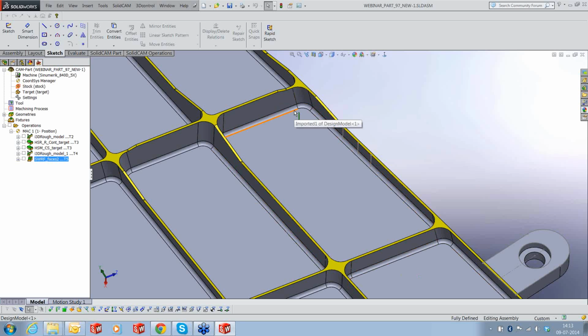Take depth of cut. Let's say even if you had taken 0.5 as a depth of cut, we would have got about 32 passes. And if each of these passes takes about, let's say, 1 minute, then to machine one pocket we would have taken about 30 minutes. Compare that with swarfing. Each pass takes less than a minute to go around this pocket. We have 4 passes, so it takes 4 minutes. So we're dropping down the machining time almost by 70–80% using swarfing. And the other best thing about swarfing is that it gives you an exceptionally high surface finish on the side walls. The surface quality is much better.